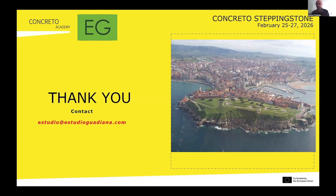And if you go in the opposite direction, there are water repellents that you almost don't see because they use nanotechnology, but the problem is when you work with graffiti or with sand and wind and this kind of erosion, it goes away pretty quickly. So I don't see another way to do something like this and maintain it. So keep applying water repellent, but every 3 years instead of every 15 years.